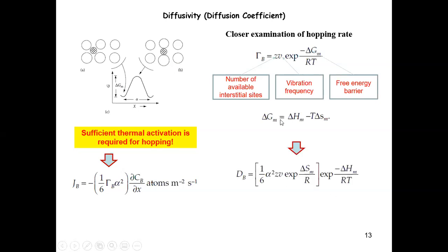So if we plug in that decomposition of free energy into a difference of enthalpy and entropy, we see a very interesting thing: the entropy contribution will not depend on the temperature anymore. Only the enthalpy contribution, characterizing the interaction of this interstitial atom with the original atoms in the system in different ways, is going to play a role together with temperature. The entropy contribution, which is fixed given the type of atoms and initial concentration, is going to be a temperature independent constant.